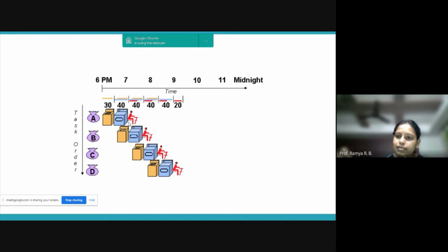See, there are other ways also to increase the performance. One is, I told you, you can increase the number of data lines in your computer. So 8-bit data bus hai to 8-bit can be transferred in one clock cycle. 16-bit data bus hai to 16 bits can be transferred in one clock cycle. 64-bit hai to one clock cycle mein you can transfer 64-bit. But we cannot just go on increasing that, because that will indirectly affect the size of our computer also. Because increasing the number of data lines means the size of your system will also increase. So there is a trade-off.